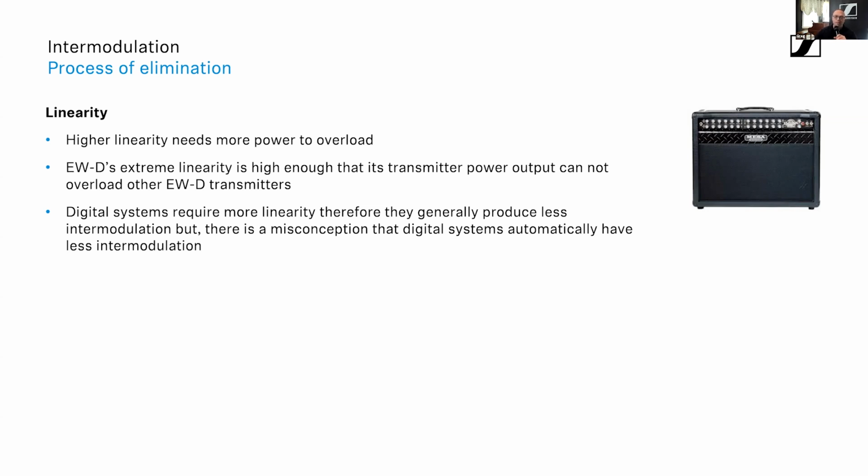Digital 6000 and 9000, and has nothing to do with them being digital. So the one thing that we want to be very clear on is the carriers that are coming across on all wireless microphone systems from all manufacturers, regardless of whether they're analog or digital, are sending analog carriers and altering them in the analog domain. That's the only way that this can be done. The difference is in an analog system, we're representing a waveform by altering that carrier. And in a digital system, we're representing a pattern of zeros and ones, or data, coming across. But the energy coming out is still the same, and the carriers are still analog carriers. I don't think there's any such thing as a digital carrier.